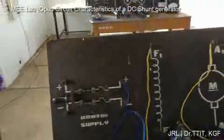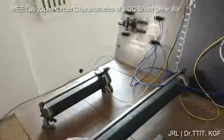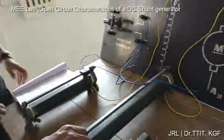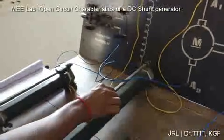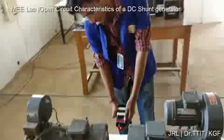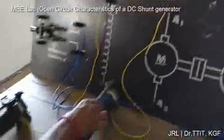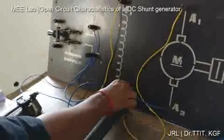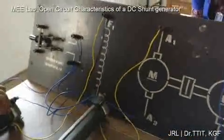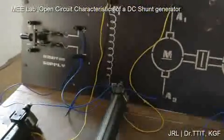The motor starts rotating. Now we need to bring the motor to rated speed. So vary the 50 ohms rheostat slowly. The speed increases gradually: 1298, 1324, 1332. Vary it fully. 1361, fully. 1382, 1414, 1439. The rated speed is 1500 RPM. So we have completely varied the 50 ohms rheostat.